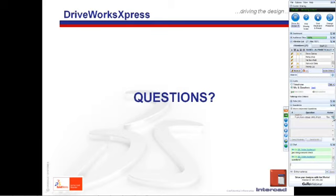Alright. The next question, if you have table-driven models set up, are they easy to bring into DriveWorks? Now, unfortunately there's a limitation to DriveWorks Express. It does not support external import of tables. In order to enable the functionality, you will need to take a look at the big brother of it, which is DriveWorks Solo. DriveWorks Solo allows you to import models with table-driven data, whether it is on text-based tables or Microsoft Excel tables. Hope that answers your question.